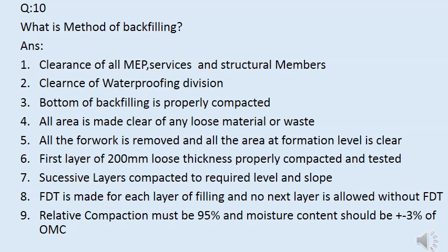and the relative compaction must be 95%. It should not be less than 95%, and moisture content should not be less than or more than 3% of the OMC. Next.